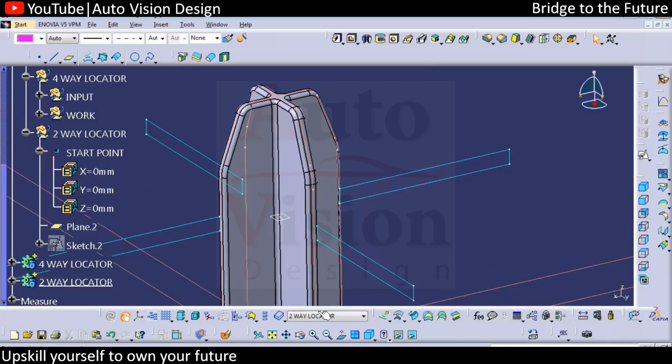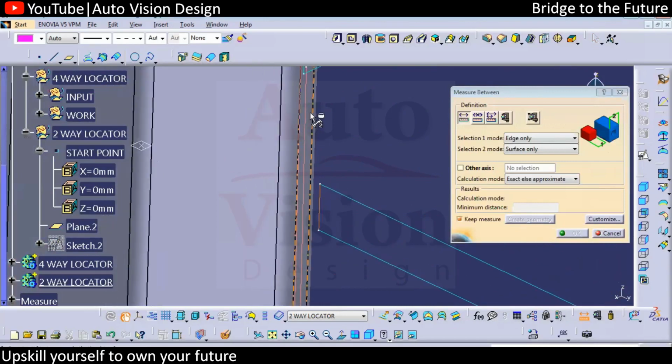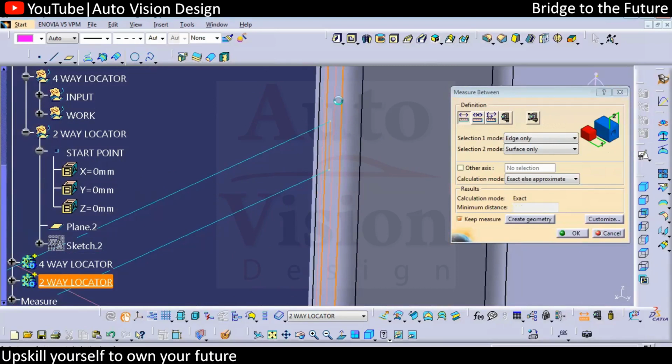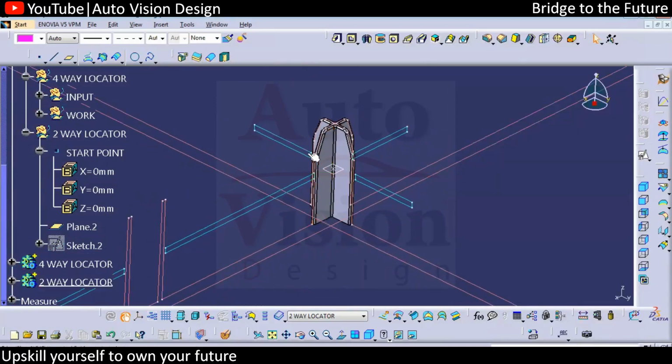Now, if you check the dimensions with respect to the given, this edge to surface, we have 0.5. This edge to surface, we have 0.1. So what is the change? The change is in the dimension of the slot, not in the locator dimension. So the locator dimension will always be the same, whether it's two-way or four-way. The only change will be in the slot.